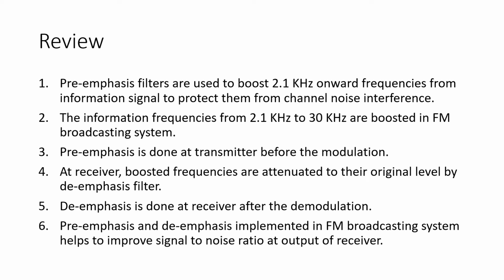Hello students, in the last lecture we have studied pre-emphasis filters and de-emphasis filters in FM system. So these are the review points from previous lecture. The point 1 is the pre-emphasis filters are used to boost 2.1 kHz onward frequencies from information signal to protect them from the channel noise interference. The information frequencies from 2.1 kHz to 30 kHz are boosted in FM broadcasting system.